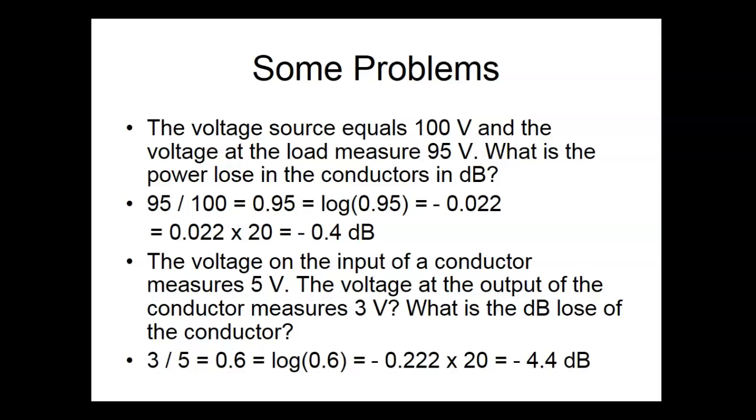Mario's going like this. Yeah, using software, they use that. Yeah, because you're measuring voltage, but it's relative to power, right? You understand? So 20 dB, V out over V in, if the load is the same, you could take the same thing and it would give you the power, right? So basically you're getting the power gain by measuring voltage, in dB.